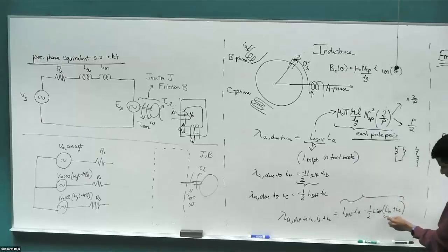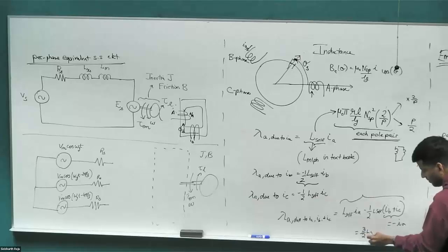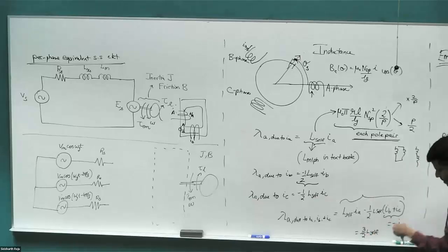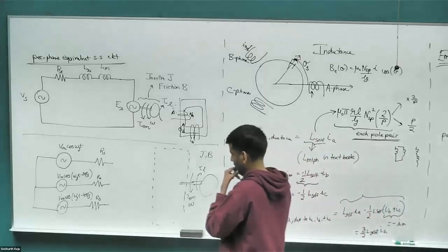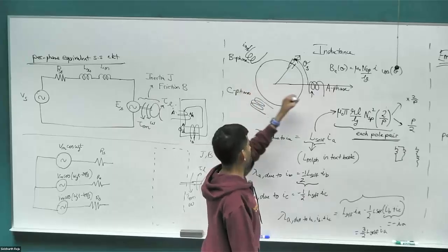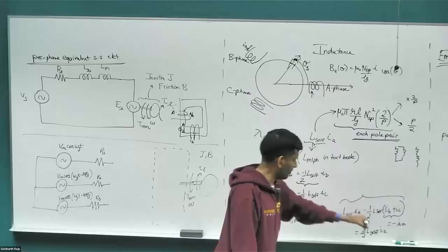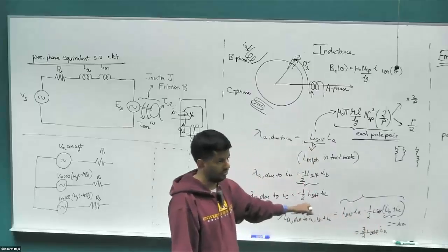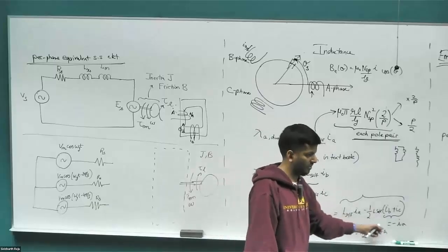Right? So when you have all the three currents passing in the coil, the net flux is going to be the sum of the three flux linkages, which is going to be this expression that we have here. This itself, IB plus IC, as we saw last time, is going to be negative IA. So we ended up with the formula 3 by 2 times L self times IA. Somewhat quite surprising and obvious at the same time, because we have three currents flowing in three different coils, but all of this information falls into just one single current at the end of the day. So the total flux linking the A phase coil is all embedded within the one single current information.